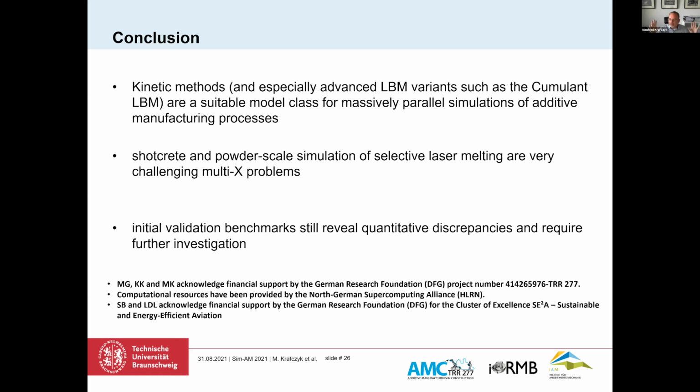Now, that's the background scenario that is known for 100 years. If you look at a more complex fluid behavior, for example a two-phase flow, you add specific components to the collision operator, and then again do this multi-scale analysis, and find out to which respect you now meet the target macroscopic equations, and you modify the collision operator until you have this. But this is only done once, of course, in the development of the model.